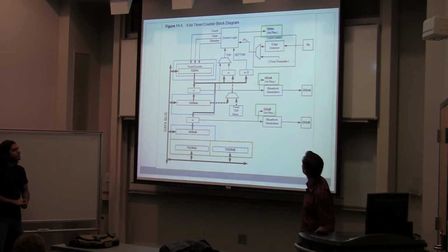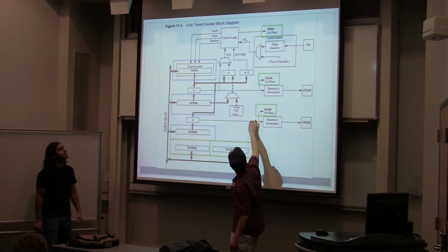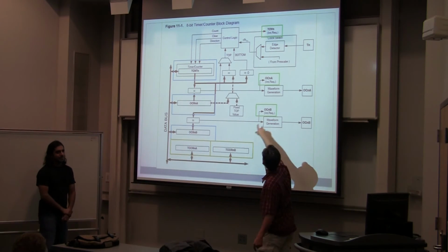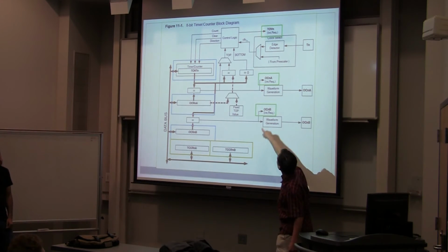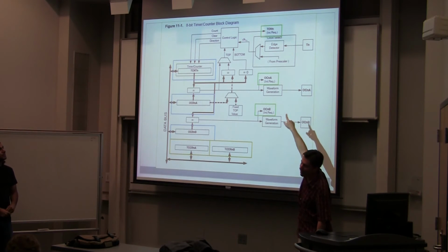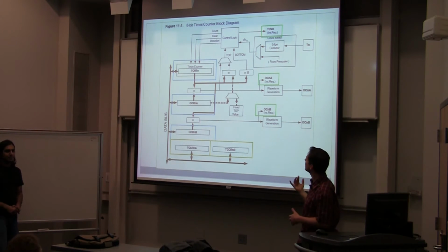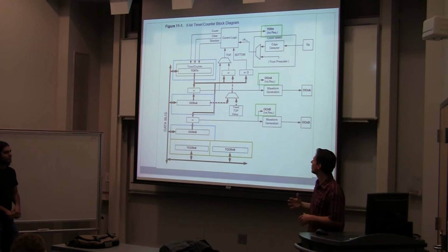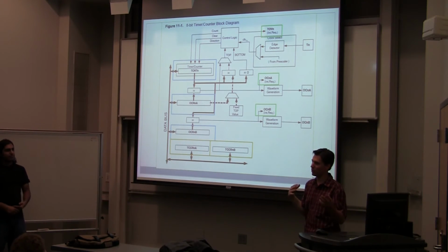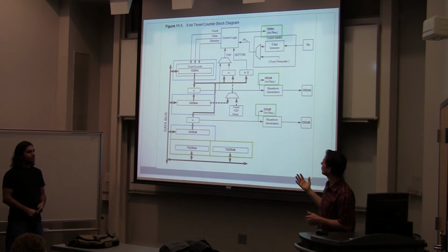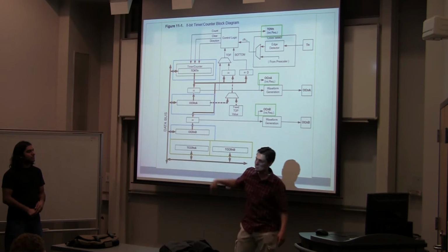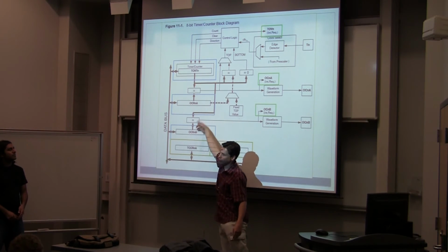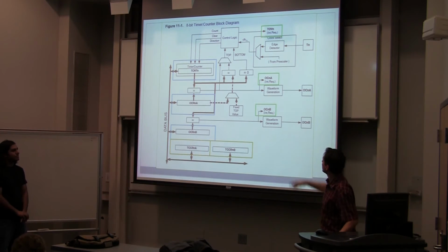Okay, and then you've got these interrupts. This one, for example, is thrown whenever the timer counter is equal to the output compare B. It'll throw the output compare B interrupt. Same with output compare A. And then there's the TOVn, which is the timer overflow interrupt. That happens whenever your timer hits top, which is actually defined by you. It's a register configuration thing, but you can define it as the maximum value, which is 255, 0xFF, or I think you can define it to one of these. So you can say the top value you can count to is 100, which I've loaded into the output compare register. And so that can throw interrupts as well.